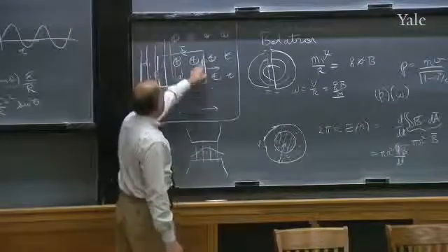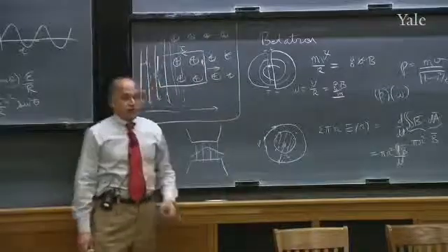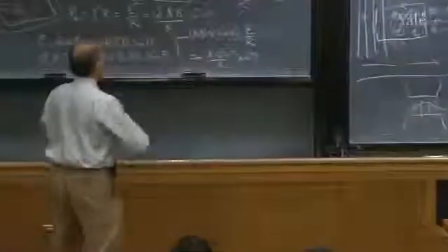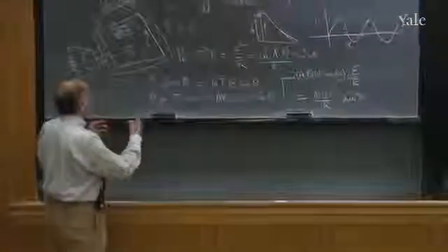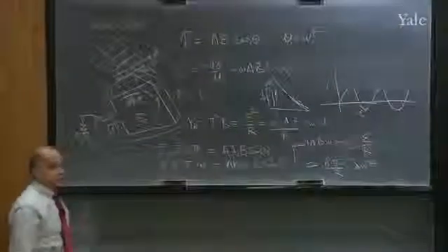But the minute a current flows in the loop, you will not be able to pull it to the right without paying the force. That force times velocity will be the power, and the two will balance. Similarly, here is a rotational problem, and the torque times angular velocity will exactly equal the power here.